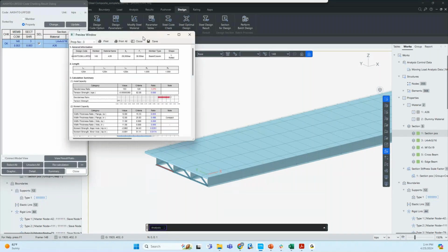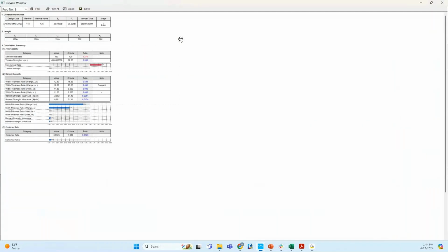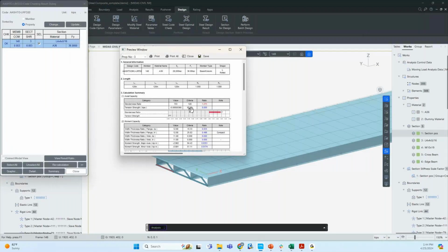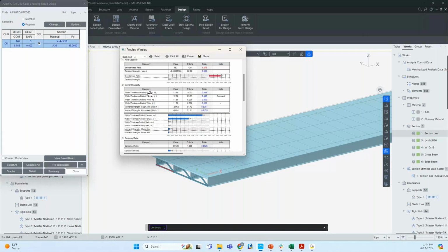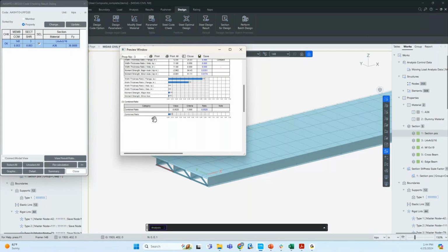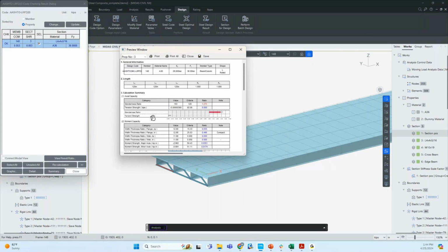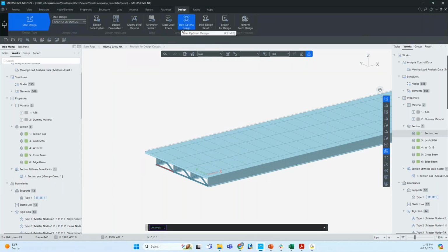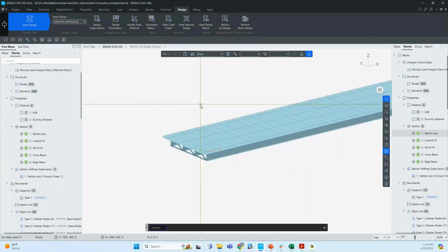And we have this kind of thorough design report for the same. So you have the members and then you see the values, like what was the category and the ratios for all. Compression ratio and the tension strength. You can also optimize, as I mentioned, the steel optimal design option is also available. So it will highlight what were the sections that can be upgraded or economized.